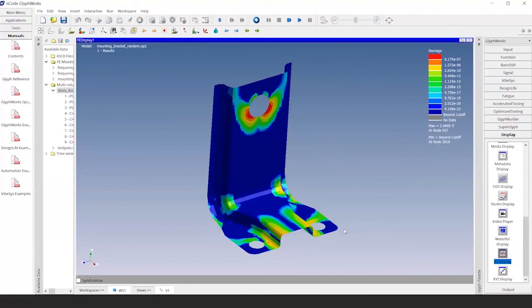This plot, in fact, looks quite a lot like the Z-axis, simply because that one was so dominant, but it is entirely possible that there could be other scenarios where you have enough excitation in the other axes that this does start to look a little bit different. And in fact, it may differ from the damage that was accumulated by doing the 3 axes independent of one another, simply because you lack the interaction that might have occurred had they all been done at the same time.